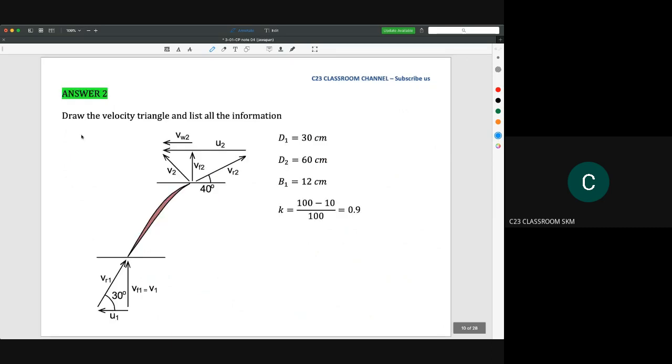Okay, first you need to draw your velocity triangle. Okay, this is the rotation direction, and then if you stay here, you are looking forward like that, you will find that this blade is actually at your back. So we call this blade a backward blade. So this is the common simple trick for you to understand to draw the backward blade.